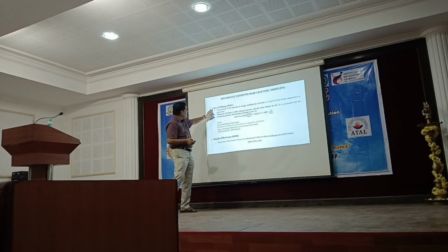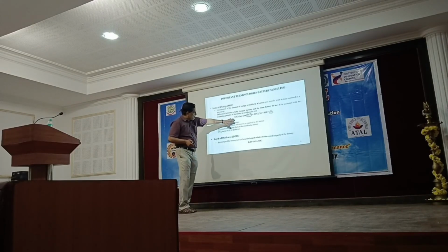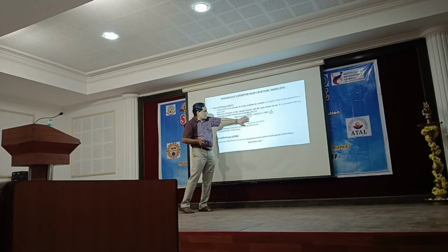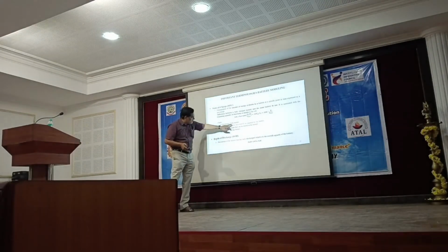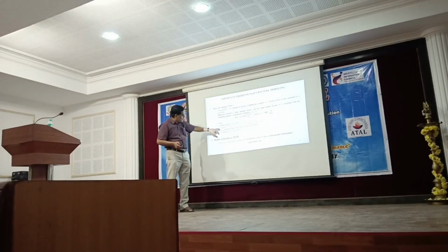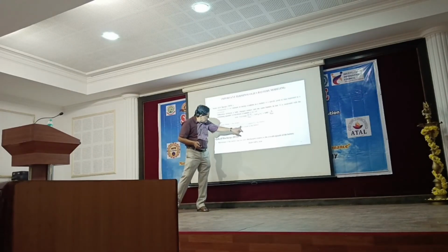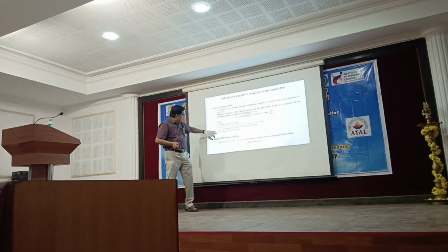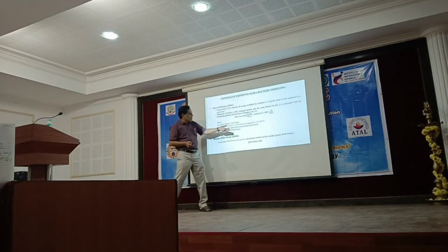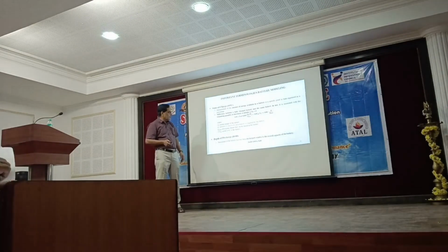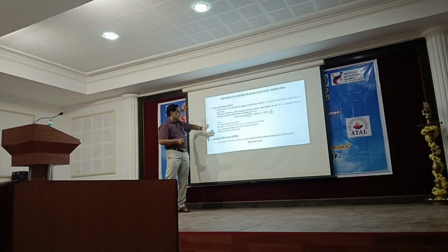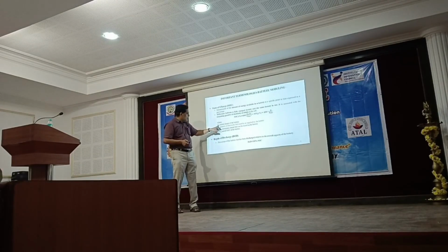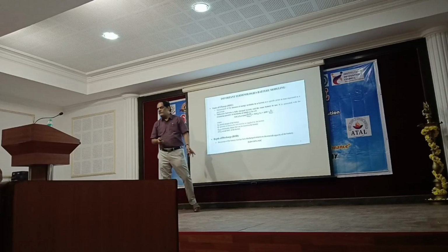Once again, the state of charge, if you want to express this, this is the typical formula. The formula we use. And again, you see the initial charge of the battery, and Q is nothing but the quantity of electricity determined by the battery. I already gave the formula. Coulomb counting, we just try to measure the current as a function of time. Once again, to reiterate what I mean by state of charge. You should know why I should care about Q0 if I ask you this formula.